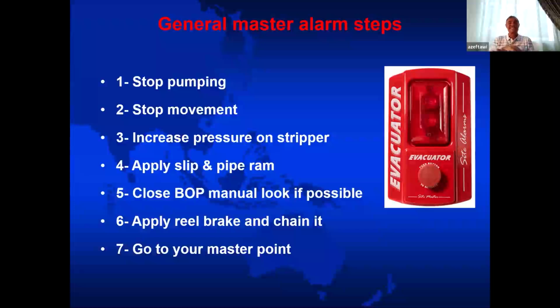You cannot put any additional single foot, but you still have 1,000 feet of pipe in the hole because the wraps are not correctly wrapped together. That's why it is very important to apply brake so you avoid this movement of pipe while the engine is running.